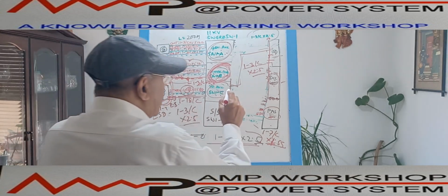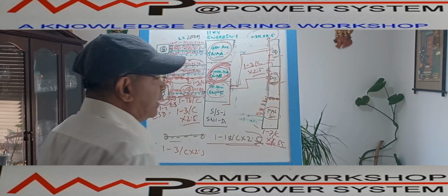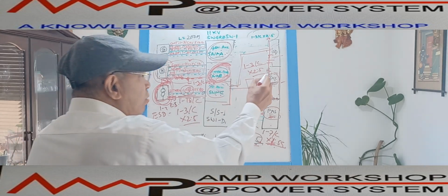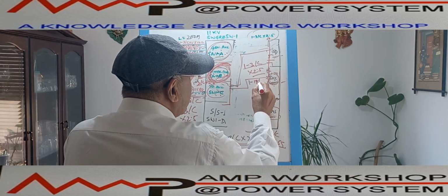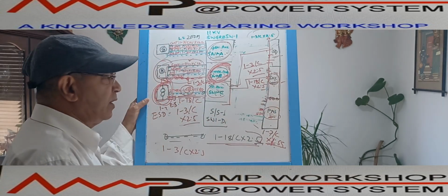Then similarly, this transformer switchgear panel will be controlled from the DCS, for the on-off control of this breaker, as well as the breaker's various status also monitored from here. For that purpose, we are laying one 18-core into 2.5 square millimeter cable. Okay, that is the DCS cable.